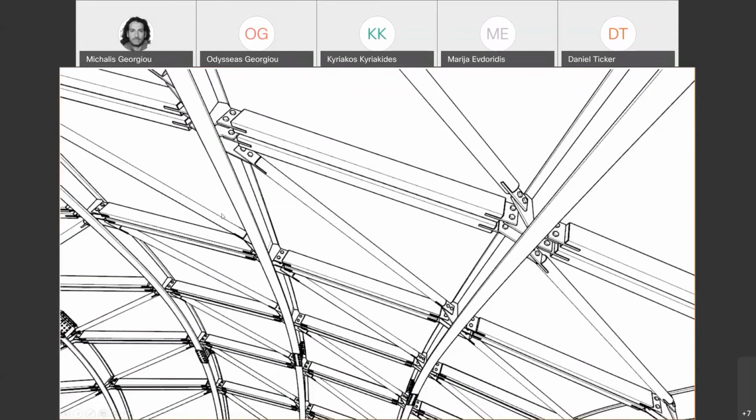The planar facets meant that the dome's framing needed to have different rotations between each frame that could correspond to the flat panels. That was approximately 350 different ranges of angles at which fittings needed to be designed and placed on the primary beams.